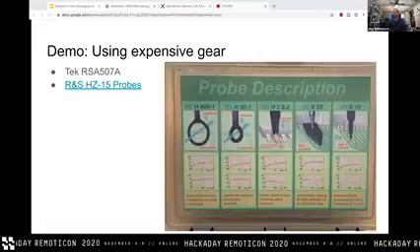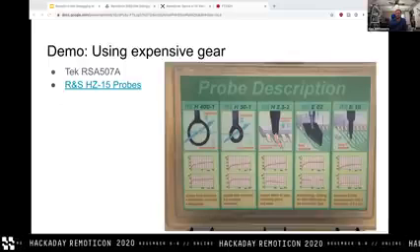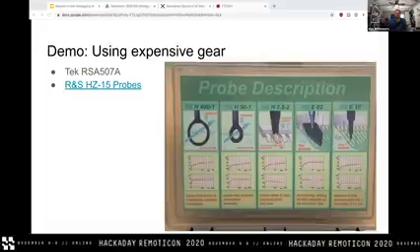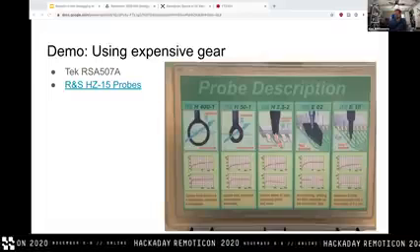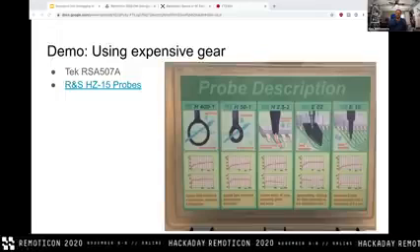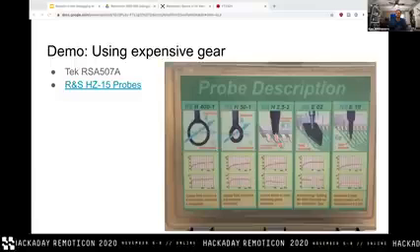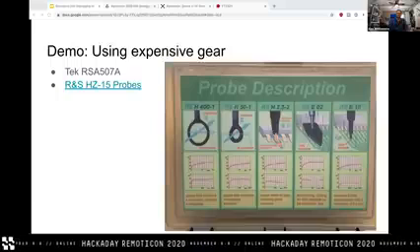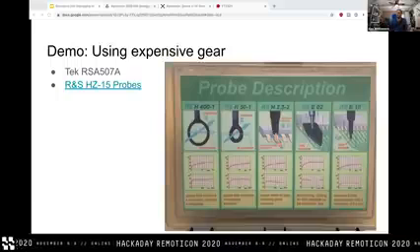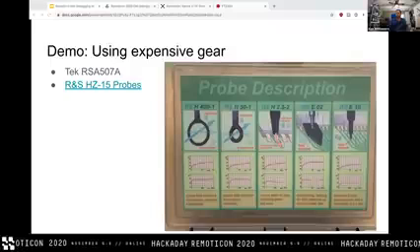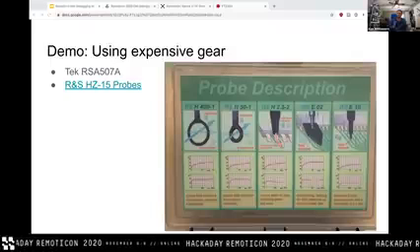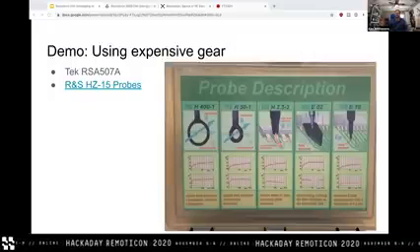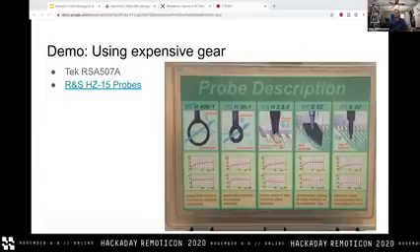As far as the RSA, I told you guys about swept spectrum analysis, where you look at one point and then move to the next in frequency and then move to the next in frequency and do that in a sweep. We can demo that with SDRs a little bit later, but the alternative to that that's basically only possible with modern instruments and tools is real-time spectrum analysis, where effectively you take a time series sample of a chunk of spectrum and then analyze it all at once, do an FFT on that time series data, and that gives you a frequency spectrogram of what's going on in the RF at that moment in time in that whole bandwidth. So SDRs do exactly this.